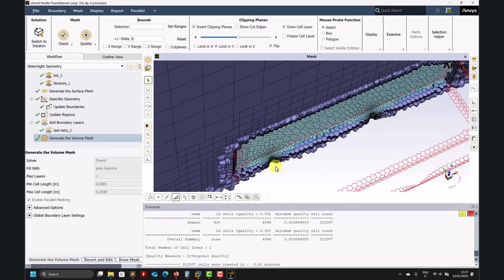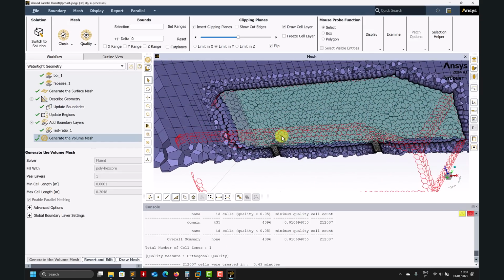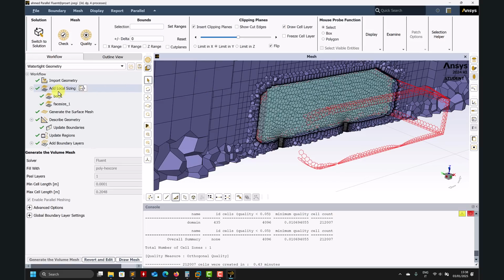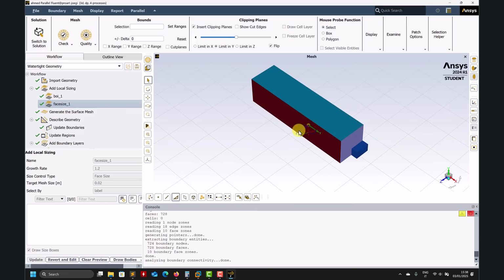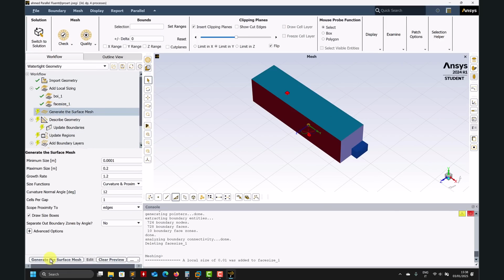So yeah, perfect. Here you can see clearly that refining the surface will solve the problems. Now we went from something quarter finer, normal to the wall. But let me go back here and add more refinement just to be sure that it will solve the problem that we have there. If I halve this, I think it should work, because we also doubled the other one.